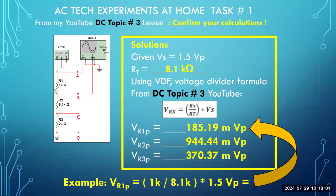First of all, the current is the same through all parts of the circuit. Secondly, there is a proportional distribution of voltages across the resistors. What this means is, in short, the largest ohmic value, right here, which is the big one, 5.1 kilo, will have the largest voltage drop, 944.44 millivolt peak. It does. Which one of these is the smallest ohmic value of the sequence of 3? The 1 kilo ohm resistor here, and that means it should have the smallest voltage drop, which it does. So there is something we call proportional distribution in a voltage divider, where the voltages are distributed in proportion, which is your formula.